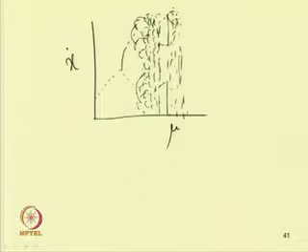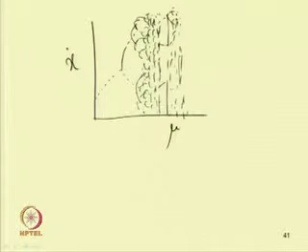Similarly, in case of quasi-periodic response, that is in case of a torus, one will have 2 frequencies. These 2 frequencies will be commensurate. So, by taking the minimum frequency, one can sample the time data and then plot the Poincare section of the system. This way one can characterize the system by using time response, phase portrait and Poincare section.